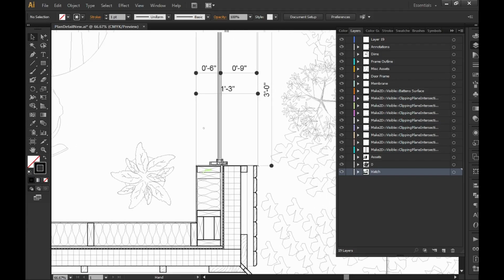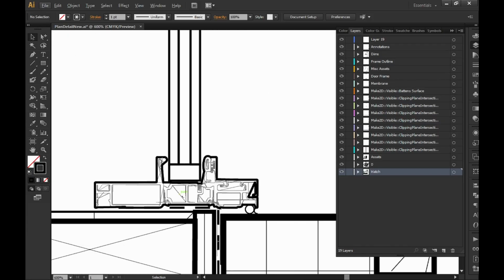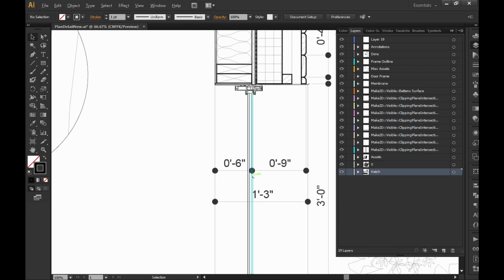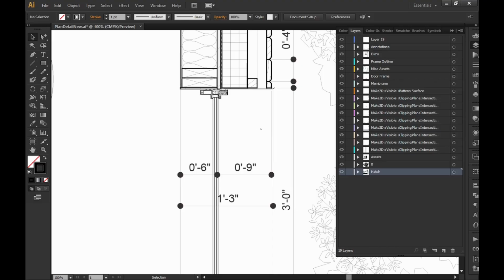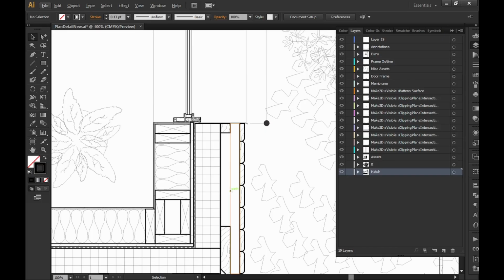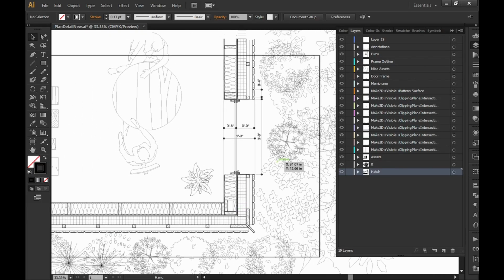But yeah, one thing to keep in mind is that everything here is a black color except, maybe, just this, because there's so much going on in the window frame. That's that. And again, there's hierarchy with what's surface and what's cut. So anything that's cut or hatch is not going to be light, anything that's surface is going to be lighter, but anything cut is going to be darker. I could make this just a little bit lighter, or a little bit darker, but we'll see how it looks. But yeah, this looks fantastic. And I want to show you 2 more things.